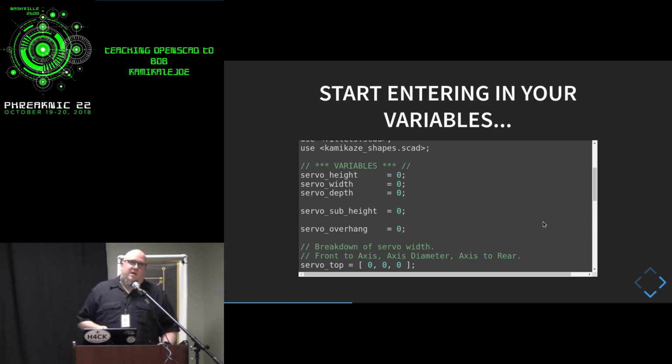So if I knew it had to be at least the size of the servo, or if I had to screw something in, I know I'm going to need the wall thick enough to be the diameter of the screw, so I would take that into account. The actual thickness and dimensions of the object are going to be heavily based on what existing hardware I'm using. The added benefit is if I can't get that same motor or servo somewhere, or I run out of those screws and have to use something different, I can easily tweak the model.